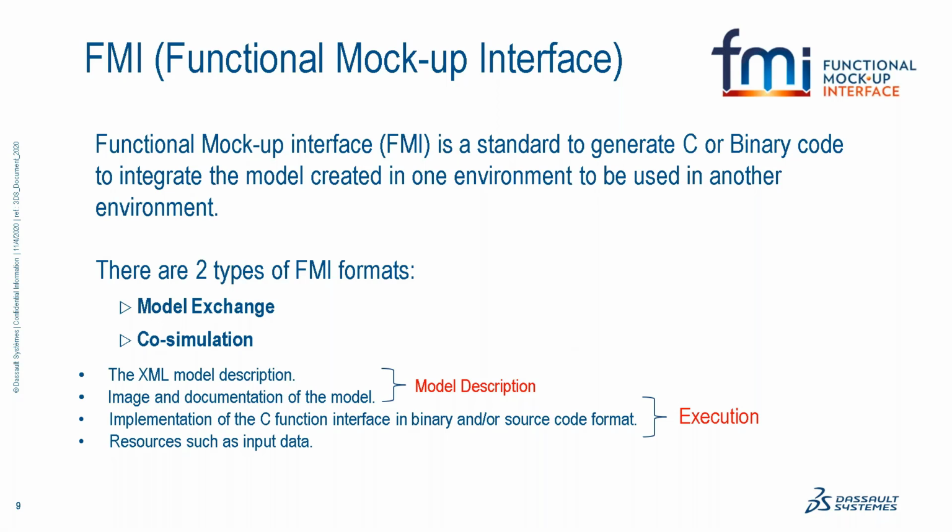It comes in two different formats. One is called model exchange and one is co-simulation. The main difference between these two is that the model exchange doesn't come with a solver, so it is always using the solver of the host. The co-simulation comes with a solver. So when you are using a co-simulation FMU, you are using the solver that comes with the FMU.